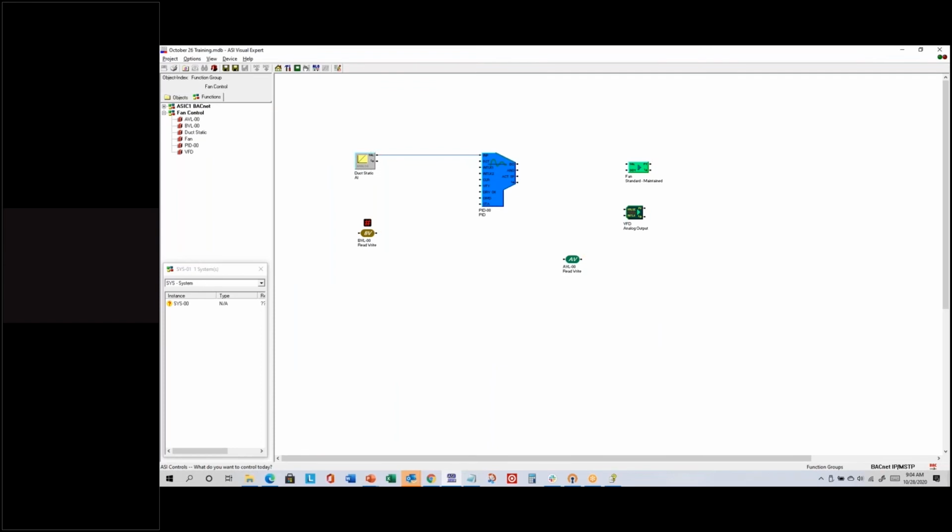So from the left side of the BV icon, I right click and drag. There's the red pound sign right above the BV icon. I drop it on that red pound sign. It asks me to enter a value. I enter 1, and then I get a gray box with 1 so that that binary value instance defaults on.